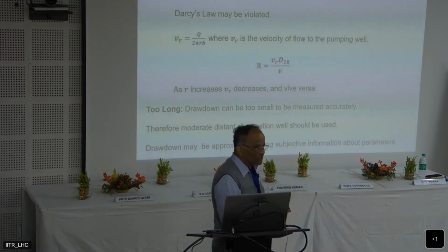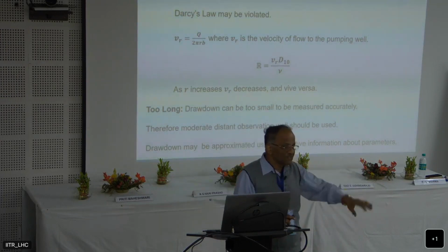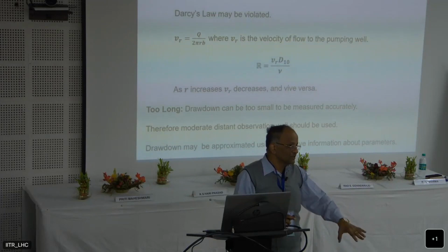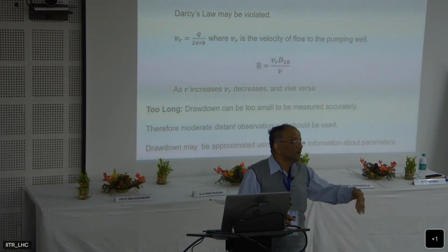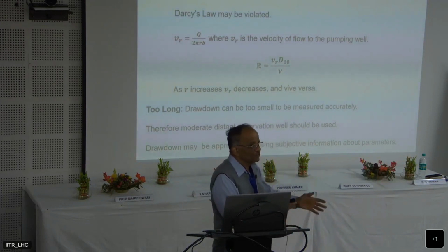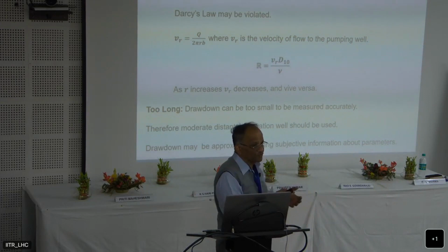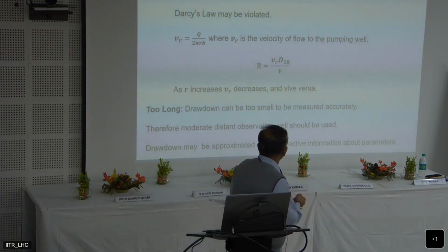So it is good to have observation wells not as close as possible to the pumping well, and also they should not be too far. They should be at an intermediate distance so that we can measure the drawdowns quite accurately.